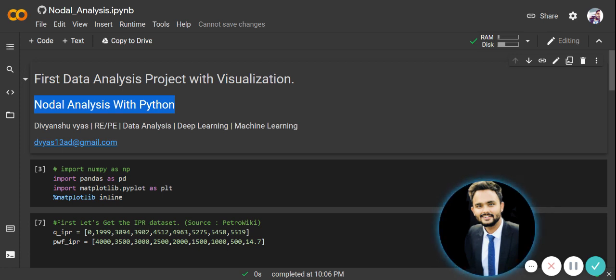So if you call the external reservoir pressure PE or P bar or anything, and the bottom hole pressure PWF, then P bar minus PWF is more like the quantification of IPR, and then PWF minus P wellhead is more like the quantification or the differential for the vertical lift performance. But focus on this single point, that we are taking the common PWF for both sides of the story. We are not taking one value of PWF for inflow performance and another value of PWF for outflow performance. So that's the important concept. In other words, this is exactly what nodal analysis is.